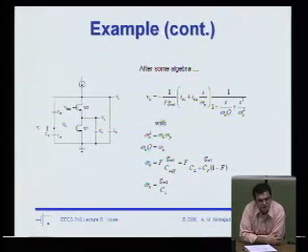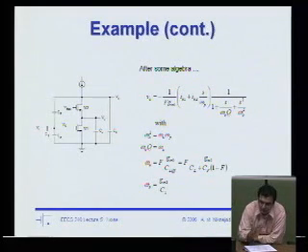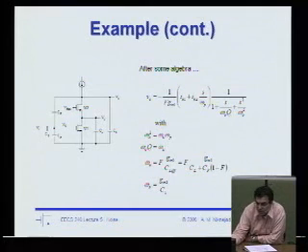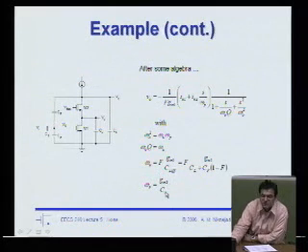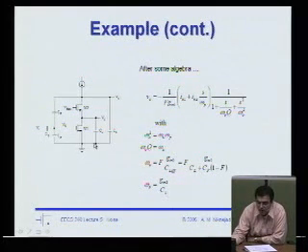The result is that the output voltage noise has basically a component that looks like this. This is the noise sources, so it's first noise source plus the second noise source multiplied by some gain factor which is frequency dependent. So the gain factor goes something like omega over omega p times some second order transfer characteristic that basically is the bandwidth of the overall circuit. Now what's really pertinent here is omega p. What's the frequency of omega p? Because if omega p is low enough frequency, the second device M2 will contribute significant noise. Well, after doing the algebra, you find that omega p is just Gm over C. Gm2 of this transistor and C, which is the total capacitance at this node, Cx.